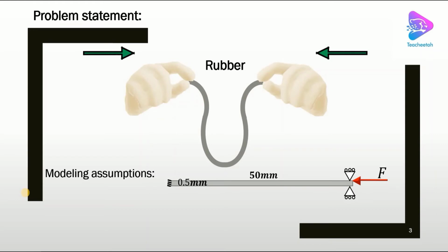As you see, I applied a hinged boundary condition to restrict the motion only in the x-axis. And as you see, the force is applied to one corner. It's not fully in the center, because the application of the force on the center and a full symmetry on applying the force may cause a global buckling rather than a local buckling. Like I said, you may find more information about local buckling and global buckling on the internet. So as I said, in this study, we have to model the system based on the local buckling of columns.